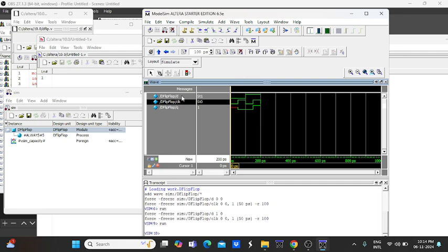So now the D value goes high because of changing this value from 0 to 1, and the clock signal again we selected with the falling edge, both on time and off time having the same duration, and in this case the input value is 1, but the clock signal is 0 here. So because of this clock signal, our output Q value is 0 here.